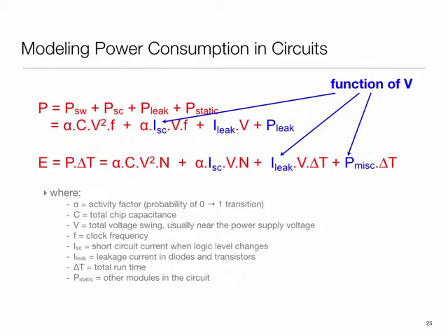And then finally, there is another form of leakage, which refers to the fact that there might be other aspects of your system where, because of circuit reasons, you are consuming power. For example, maybe somewhere I have a very high resistance between power and ground, and therefore there is a continuous leakage happening. Analog circuits could be of that nature. As long as we are powered up, this will keep happening.